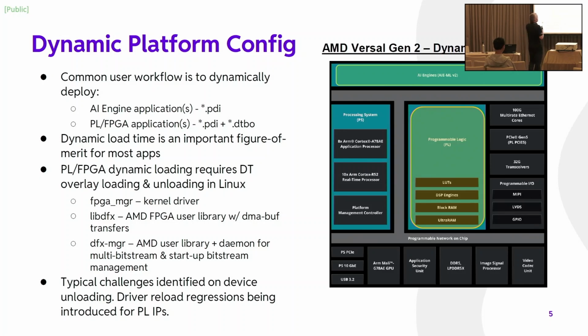So this is an aspect of why that dynamic platform configuration is important. It has impacts, like I said, in terms of Linux kernel capabilities, Linux kernel configs, and just basically device tree overlay enablement in general upstream. So the capability is there, but upstream kernel does not enable it by default, and so that's something we're working with the team on.